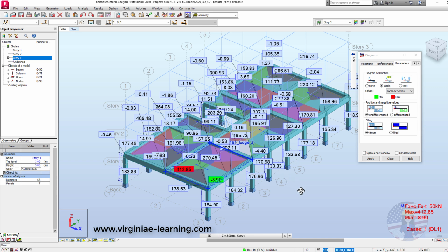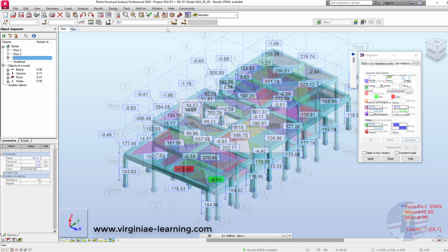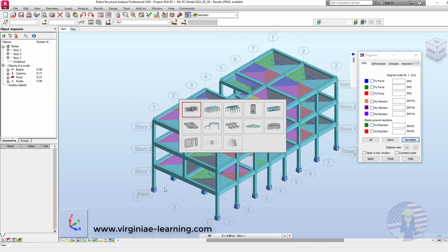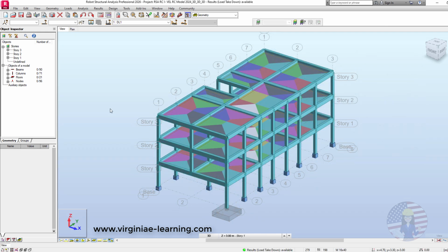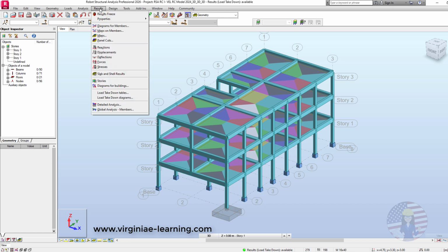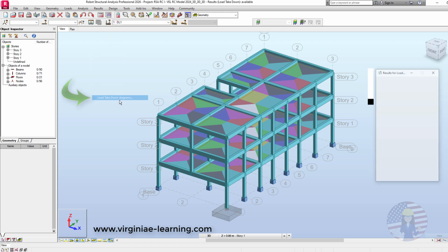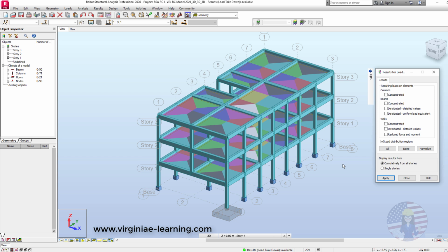So it's in cases like this where load takedown analysis can really help. This type of simplified analysis allows us to quickly spot any lack of continuity in the way gravity loads are being transferred through the structure. So let's now take a look at this model using the load takedown building design template and see what insights we can uncover. To start, while working within this template, we can open the Load Takedown Diagrams dialog. Among other options, this dialog allows us to quickly visualize the load paths affecting the columns, along with the resulting reactions for each active load case.